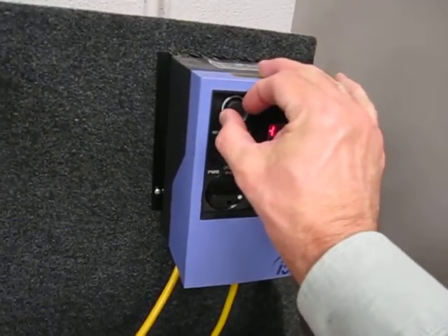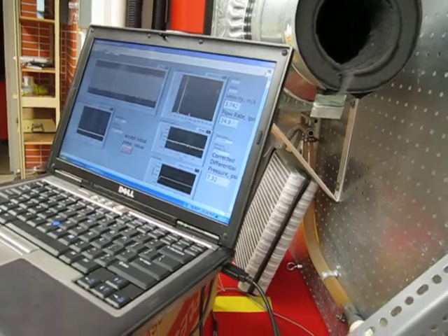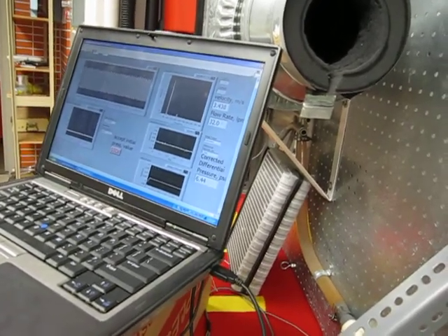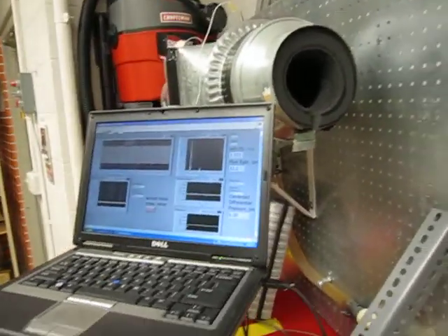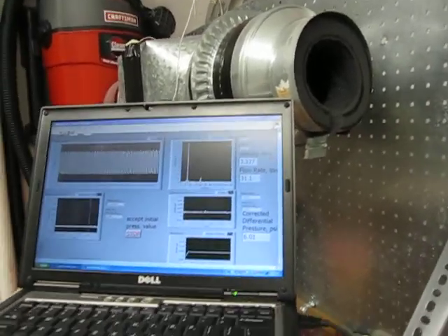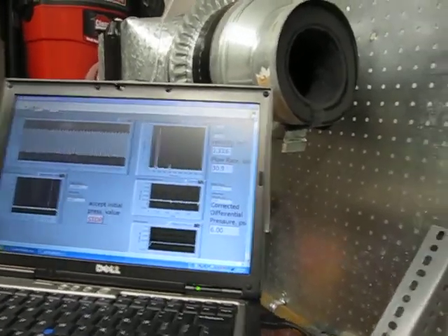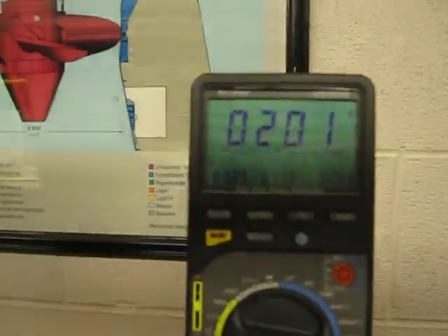Then we want to slow the pump down. We'll slow the frequency down. We're going to look for about 30 liters per minute over here. Probably can't see that, but slow it down until we see about 30 liters per minute. About like what we did with the first set of data. And just let it sit there for a while until it stabilizes. It takes a while to stabilize because the fluid is surging. We can't see it very well. Once we think it's stabilized, then we will read the flow rate, the pressure differential, and the power that's used.